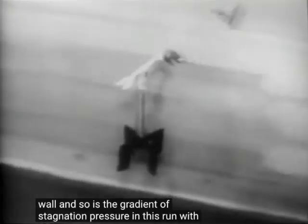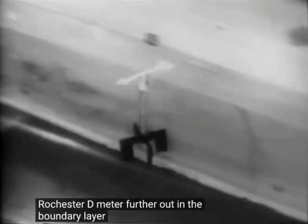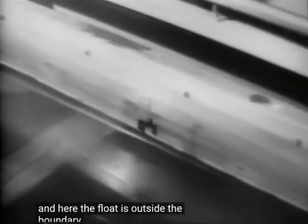In this run, with a vorticity meter near the wall, the rate of spin is quite large. Here, with a vorticity meter further out in the boundary layer, the rotation is less. And here the float is outside the boundary layer and is not spinning. As it moves downstream, however, it enters the boundary layer, which has grown thicker, and finally begins to turn.